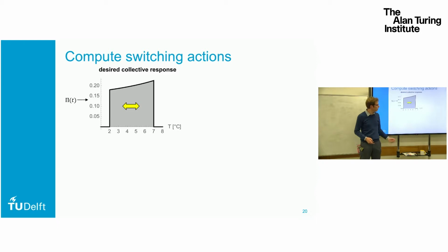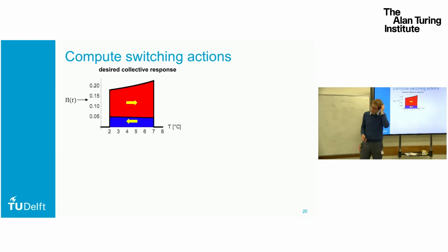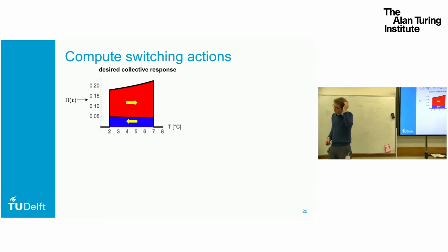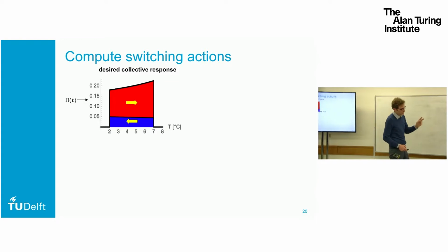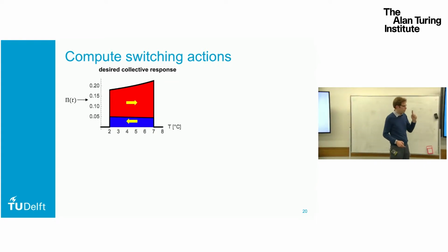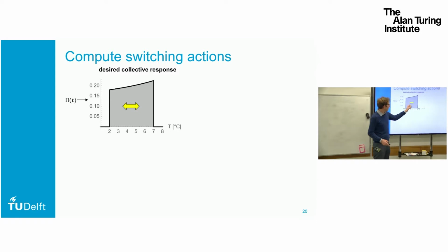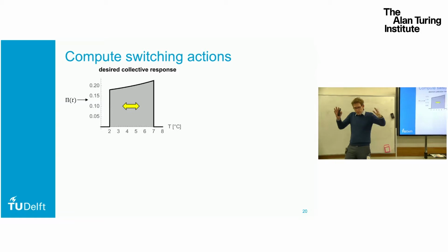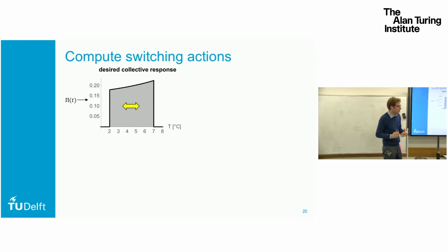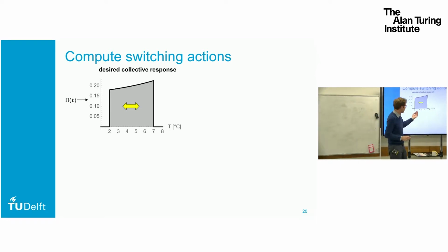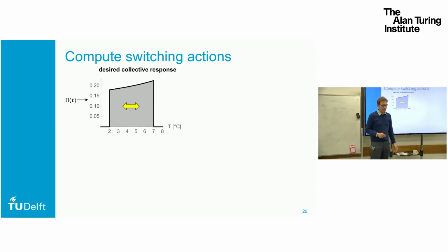desired population behavior. We then say, okay, well, this population behavior, an individual fridge can only really have two behaviors. In our case, it can be on or it can be off, right? So if you see a certain net velocity here of fridges of this temperature, let's say all fridges of temperature 5 degrees, this flow of probability density is such that the average flow speed is, let's say, +1 degree per half hour.